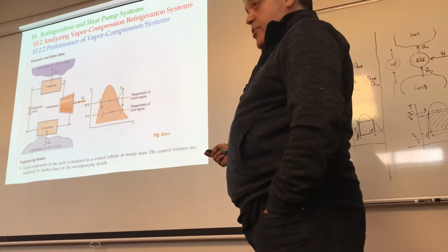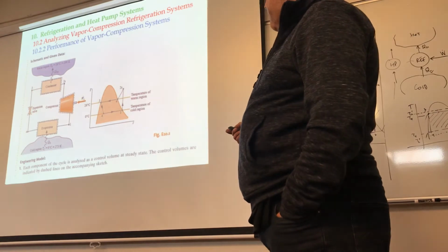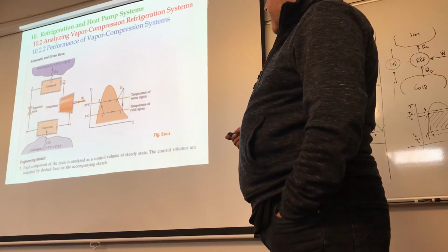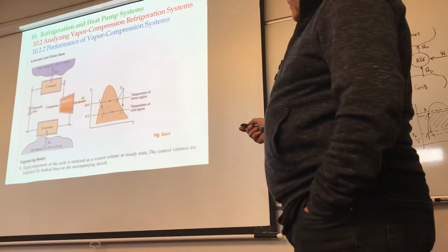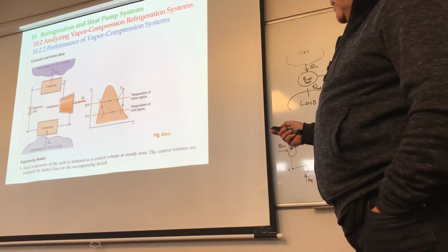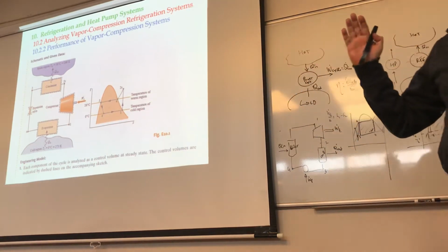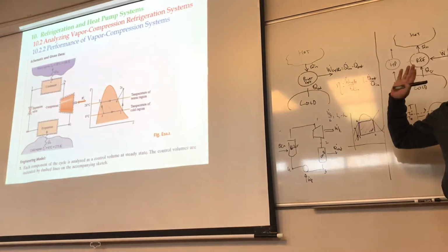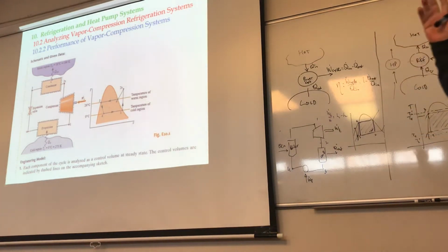QC is 0 degrees, which is 273. TH is 26, which is 299, right? And this is showing the ideal cycle, right? Starts at saturated vapor, isentropic, finishes here at saturated liquid, little increase in H, and you move on, okay? And as is the case for vapor power cycle, to do this one, you just need to find what the 4 H's are. Right, so once you find those, then it's a no-brainer.